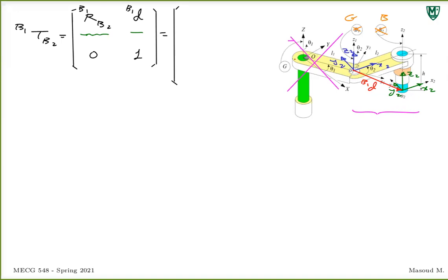So you had the rotation, theta 2 amount about the z-axis, z1, which is z in this case, right? So we can write it as cosine theta 2, that's just rotation about the z-axis, minus sine theta 2, sine theta 2, cosine theta 2, 0, 0, 1, 0, 0.